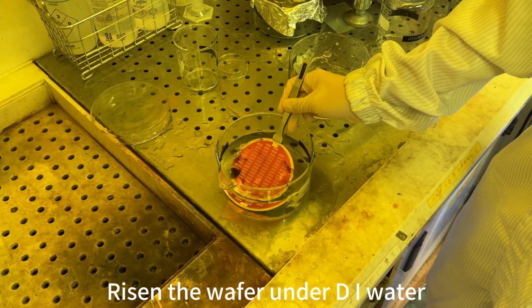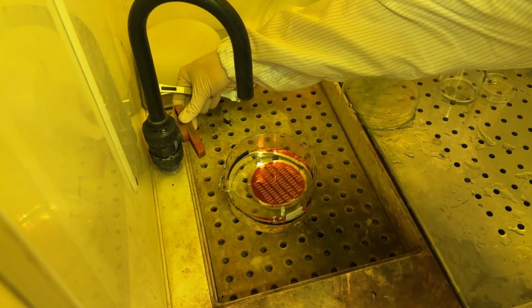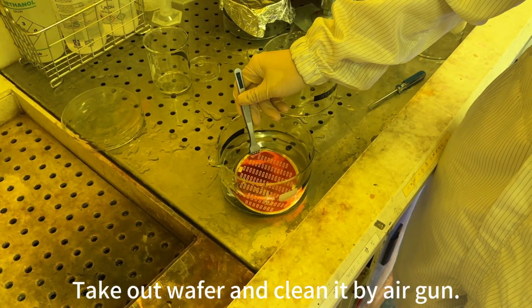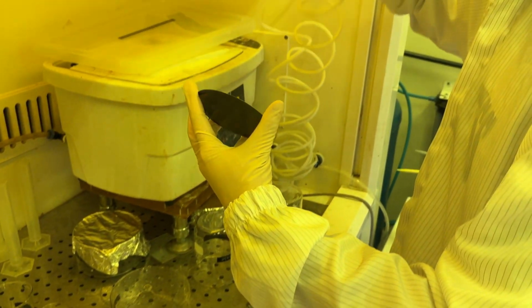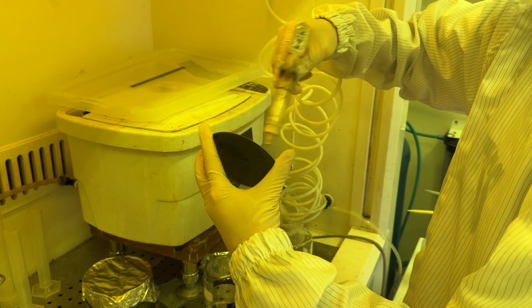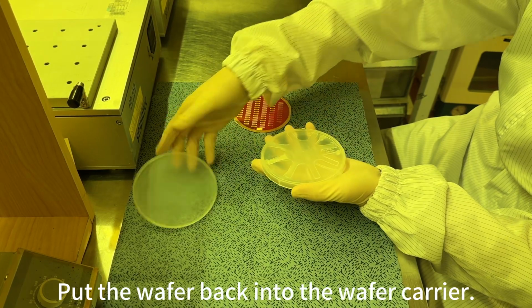Rinse the wafer under the DI water. Take out wafer and clean it by air gun. Put the wafer back into the wafer carrier.